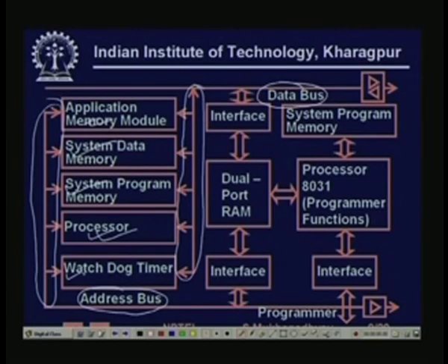Special kinds of PLC systems are different. Just like you must have experienced that sometimes your PC hangs. It just sits quiet doing nothing. Somehow it gets mired into some infinite kind of loop. So this is prohibited in PLC systems, if due to reasons like wrong programming or memory corruption the processor stops doing useful work, then there has to be explicit mechanisms by which the processor execution must be brought out of it and taken into a safe state.